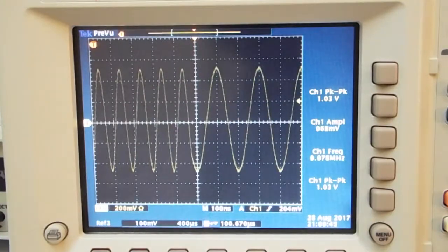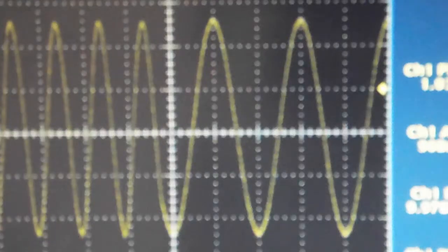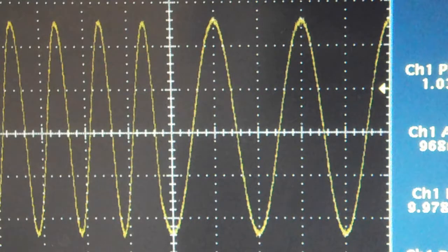One advantage of DDS technology is the ability to change frequencies in a phase-continuous manner with no phase discontinuities. We will do this switching from 10 MHz to 5 MHz on the oscilloscope. This oscilloscope image is a capture of the 409B changing from 10 MHz to 5 MHz in a phase-continuous manner while in phase-continuous mode. It can be seen clearly that as it changes frequencies, there are no phase discontinuities.